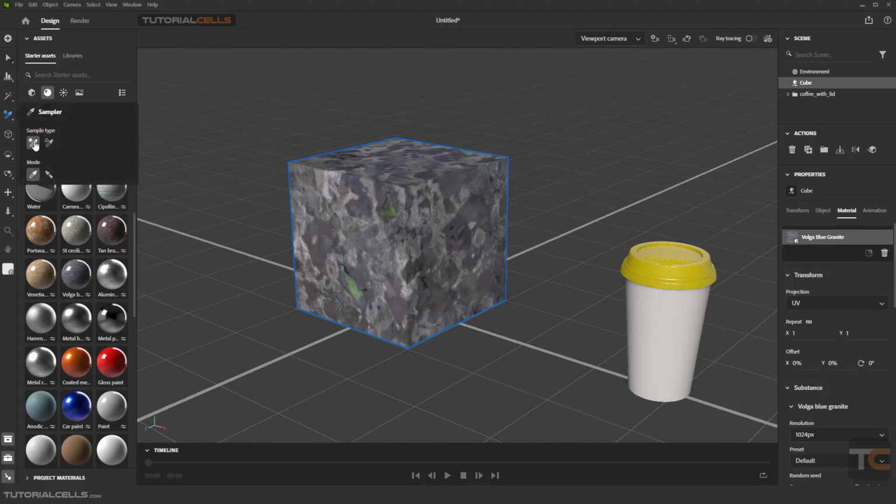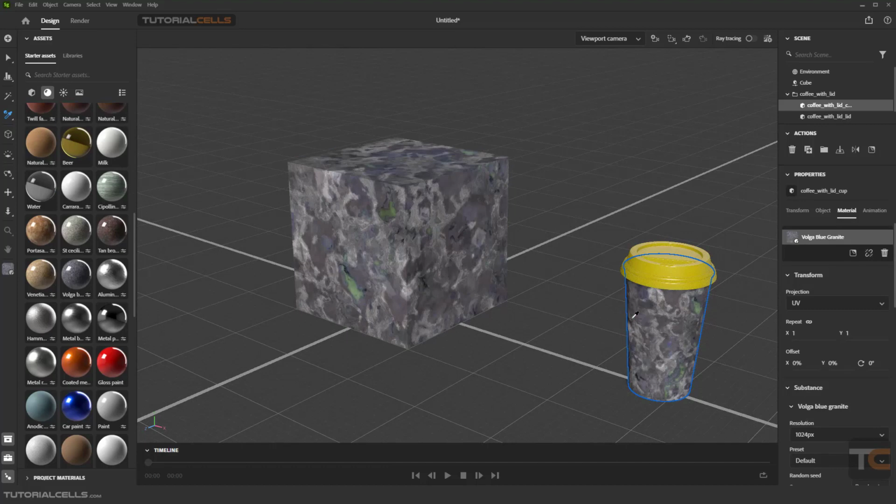So we have two tools, material picker or color picker. Color picker is just a color. Material picker is very simple. Click it to select it and it's selected. And as you can see, it's defined here. And then you can, with holding shift, as you can see, look at the mouse shape. This is a picker. Holding shift, this is an applier. You click, pick this material, then holding shift, or you can come here and go to the apply mode. As you can see, holding shift, it's going to the apply mode. And then click here. As you can see, we sampled this and transferred to that.